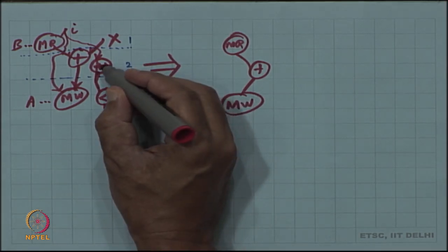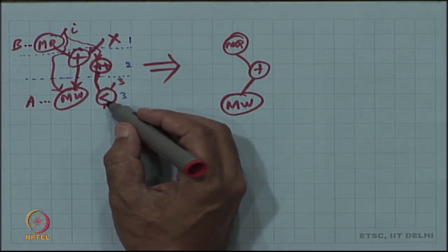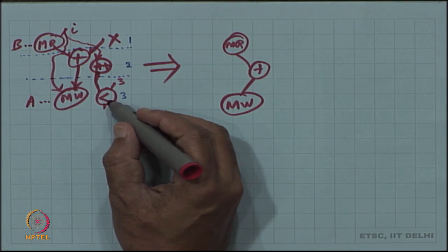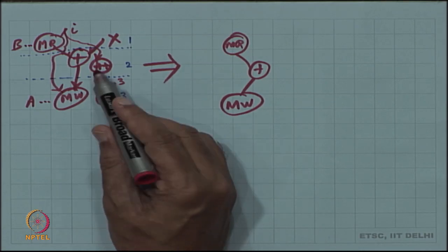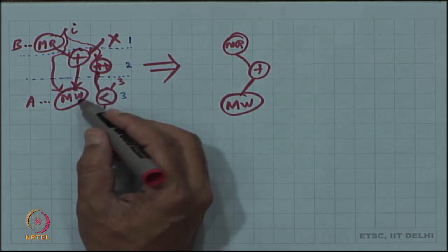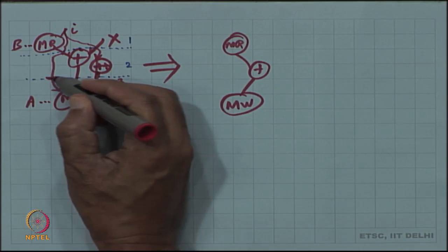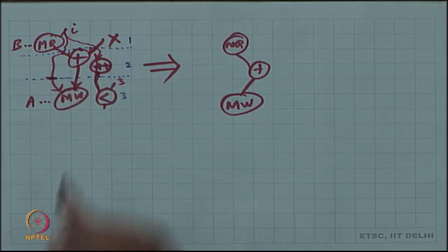For example, you just determine the value of I plus 1, and that value is used for the comparison, which is fine, and the actual update of I happens perhaps by the end of this, because this is registered, and therefore simultaneously with the memory write, you could have the updating of I.